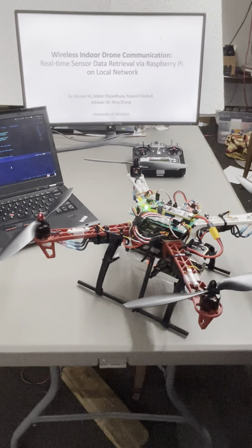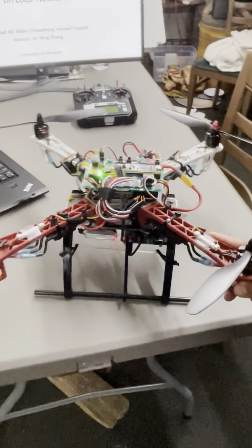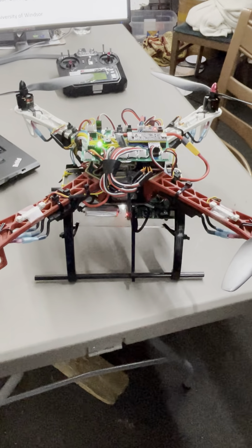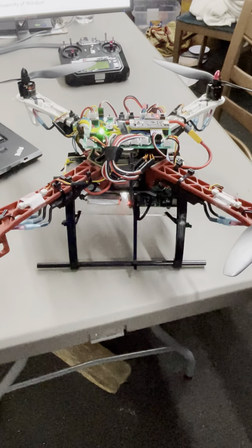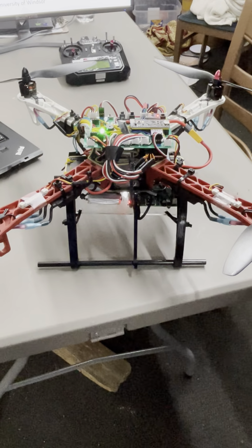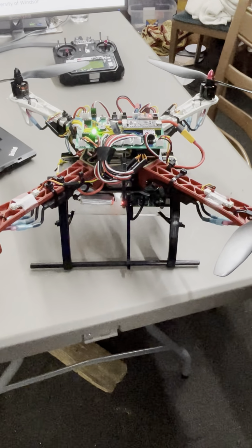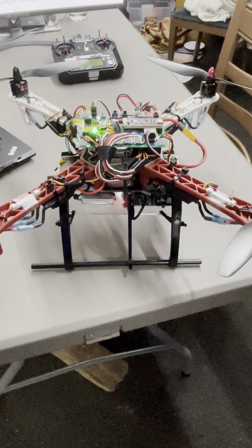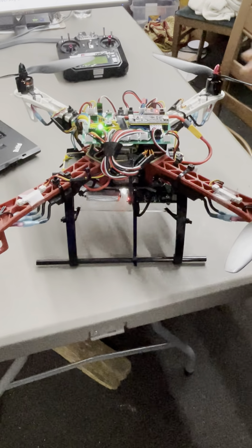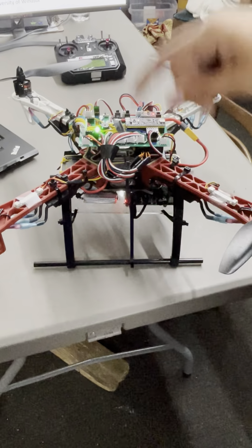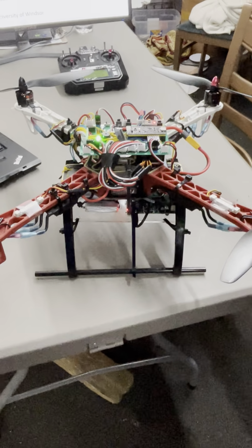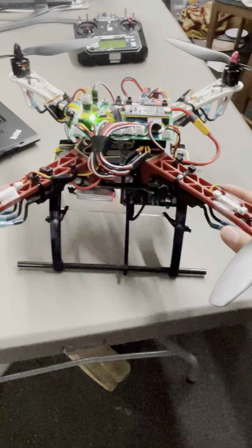And so why is it important to establish a communication between our drone and the ground station? Well, oftentimes you're going to be performing high-level processing such as machine learning, visual SLAM, and visual geometry. To do this, we need to be able to take the sensor readings from the microcontroller and send it to the Raspberry Pi, which will then act as the communication hub to send it over to the local network using sockets.